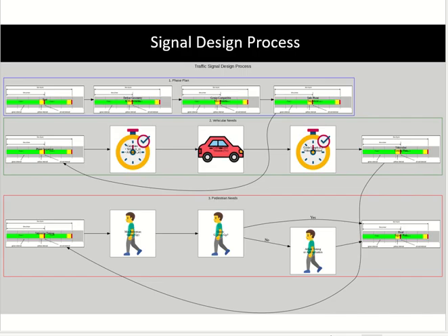Then once you have done that, we calculate the cycle length. We have calculated cycle length earlier. So whatever you need in that equation, you must have it. In that equation, we need critical volume, we need loss time, we need phases. So all these things will be there. Now we move on to the cycle length. Clear?